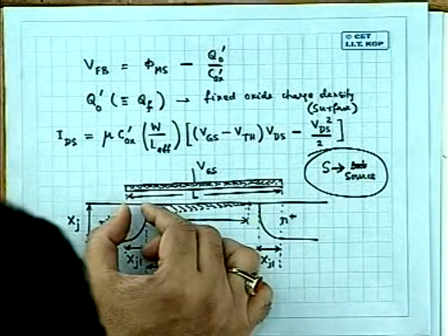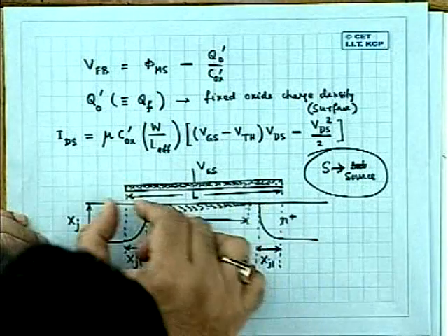And then suppose L effective is 5 micron. Typically we used to keep L, this one, the length which is defined during the patterning of aluminum, about 1.5 times or sometimes double the value of L effective, so that I always get an overlap on this side and that side.